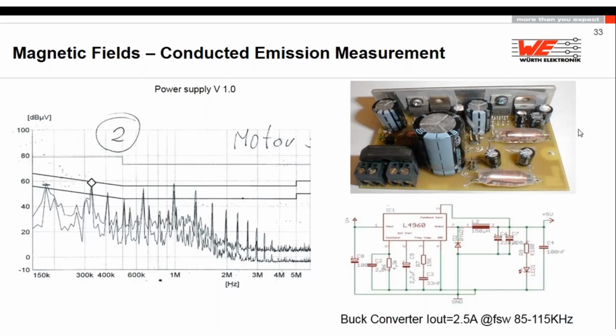It's a dual layer PCB. We had the idea: please change these two inductors to shielded ones, flood the top side with ground, make vias to have a good ground plane, and try this again. He goes back to the EMC lab. The EMC lab looks at his schematic number one, schematic number two.